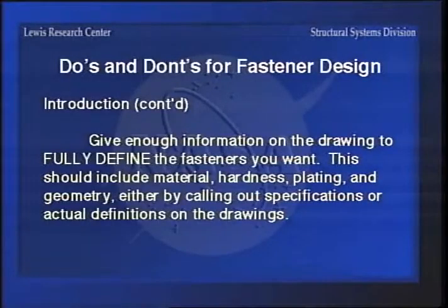So this is why I said fully define the fasteners you want. In other words, when you call them out for a specification, give the paragraph of that specification that covers the fasteners that you want to use. Or if you are not satisfied with how it's defined in the spec, give the strength level required.